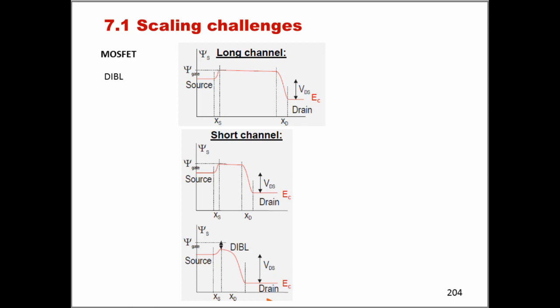And this process of shrinking a long channel transistor into a short channel transistor is highlighted by this sequence of diagrams. So we shrink when we move in the downward direction here, and so we can visualize what is happening to the energy diagram of my channel as we move this way, and so we can visualize the DIBL effect, the drain-induced barrier lowering that we just mentioned.